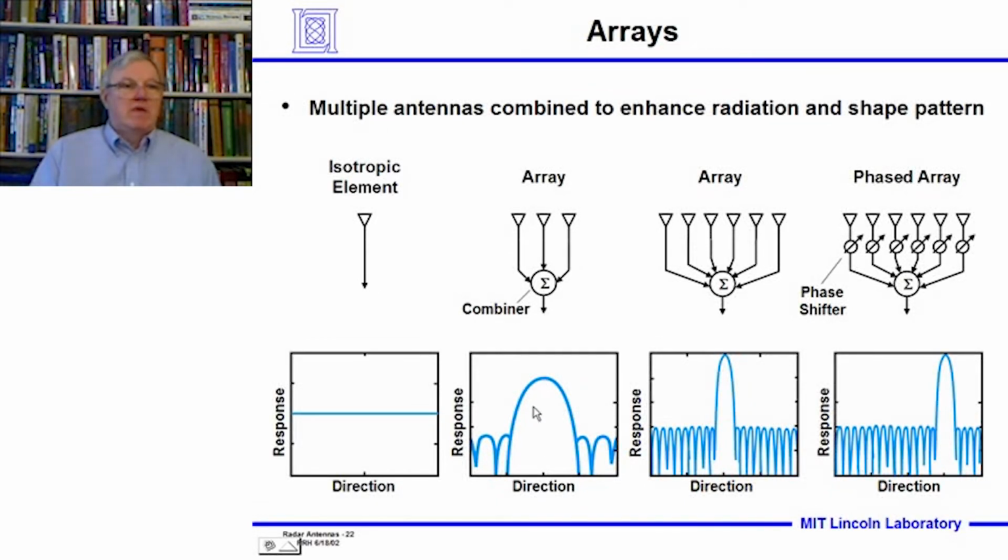And I'll just say as a caveat that the distance between these little elements of an array antenna is less than half of the wavelength of the energy we're radiating. And what we get is one big bump. Let's say they're half a wavelength apart. So we've got a total of a wavelength here. And then here we have 1, 2, 3, 4, 5, 2.5 wavelengths.